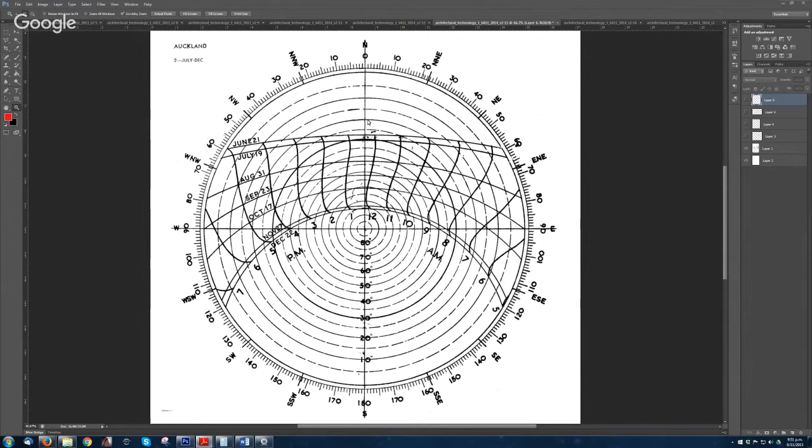And if you're looking at east of north or west of north, always use north as your datum. Don't ever say south of east or anything like that, because the degrees always start at north 0. Everything works off that all the way around. So yeah, east of north or west of north.